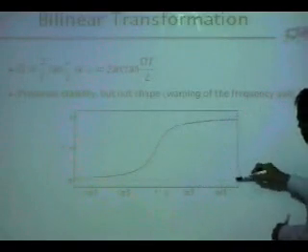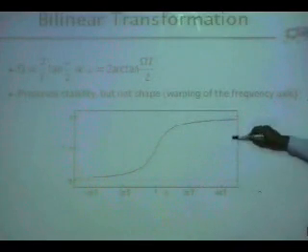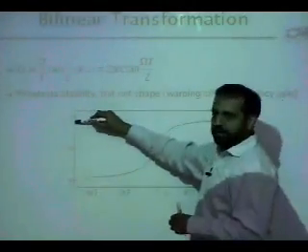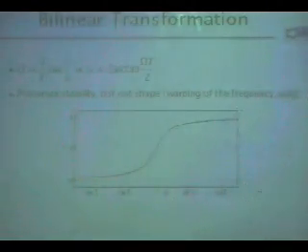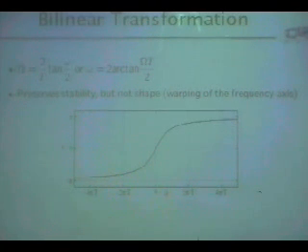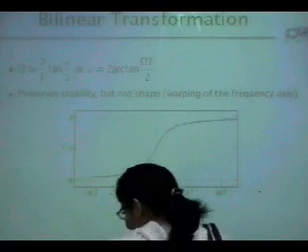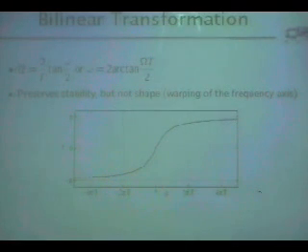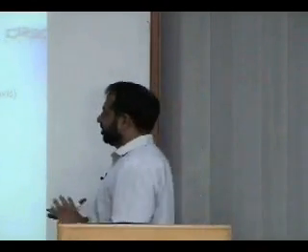So as you can see, no matter where you go, once you read a value and try to find out the small omega, it will always be within minus pi and pi. Because everything is within minus pi and pi, once you make copies of it at every 2 pi, there will be no aliasing, guaranteed. No aliasing means that if your analog filter is meeting specs, it is guaranteed that this will also meet specs. Aliasing will not cause what happened in the impulse invariance method, where due to aliasing your digital filter is no more meeting specs. This will not happen here, okay, guaranteed.